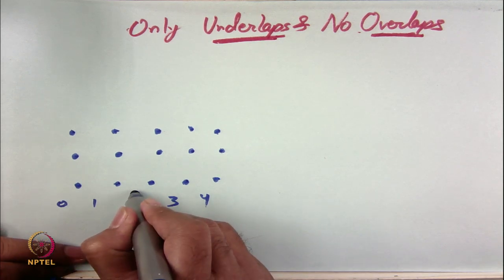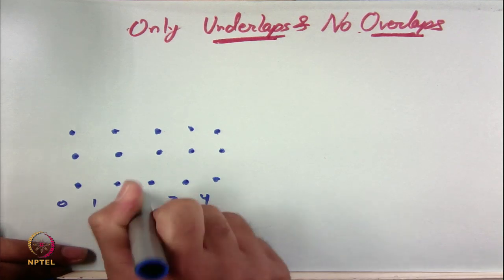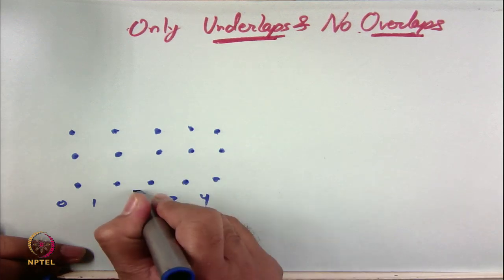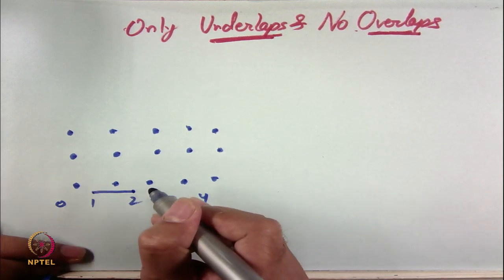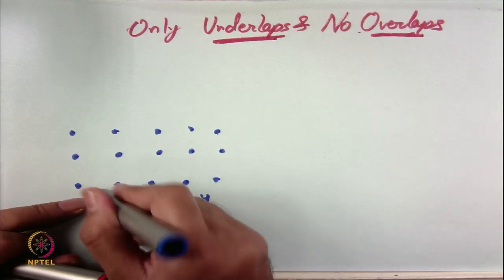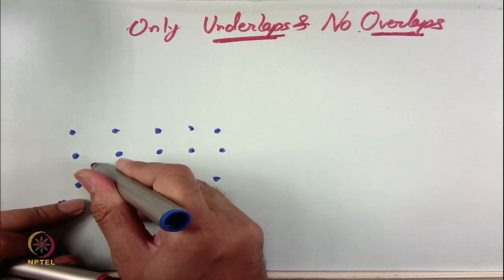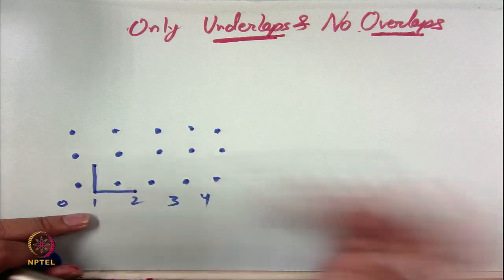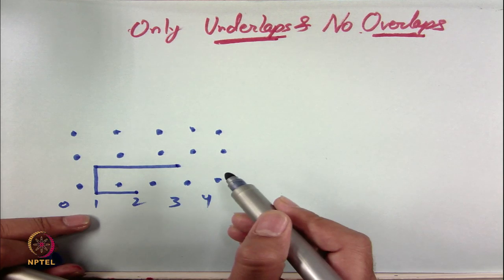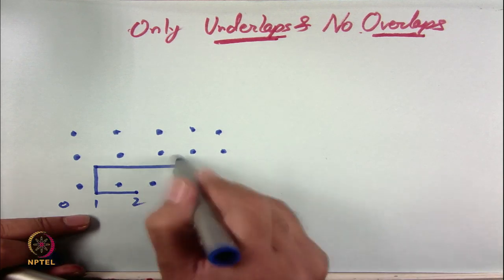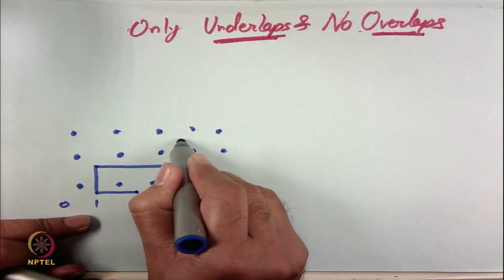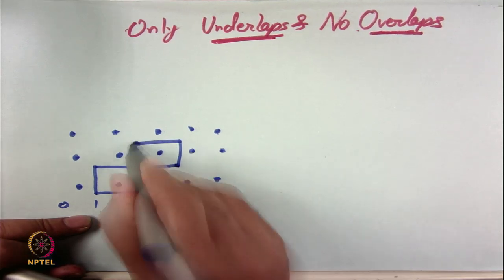So, the yarn does not do overlap. It swings again, comes back, and then it is doing the underlap at the back side. Again it swings on the same position, no overlap to any needle, it again swings to third position, this is the third position, again it swings, no overlap, and it reaches back to second position.